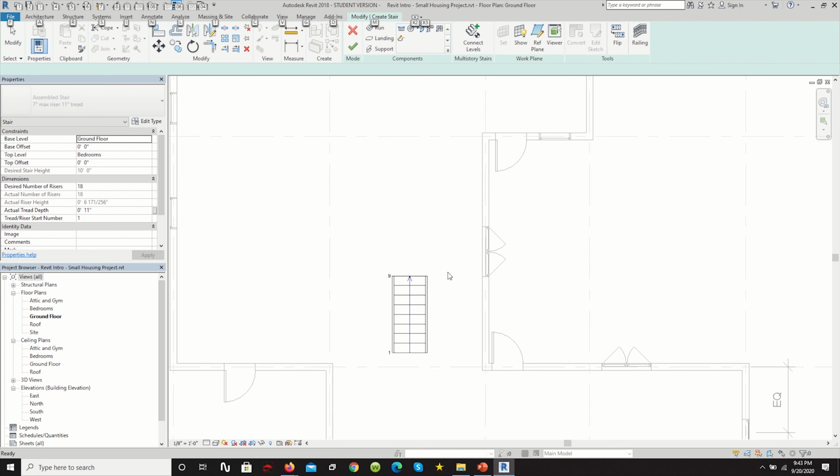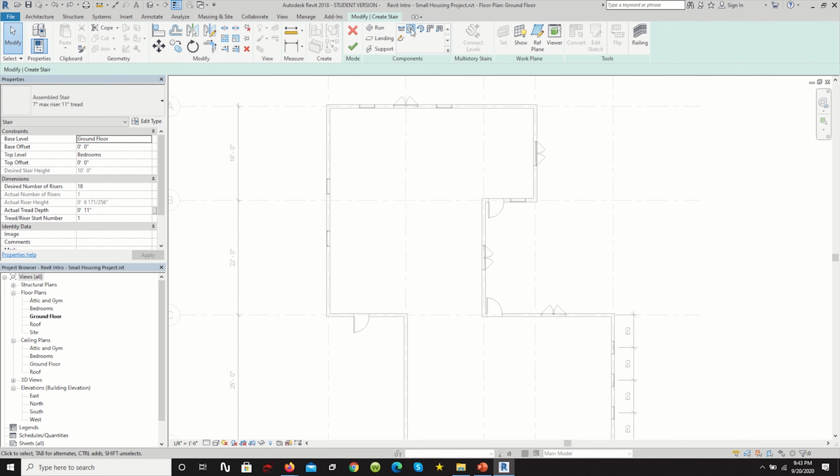And another way, Control Z, another type of stairs, you have the spiral stairs that you can work on as well. First, you pick the radius of the stairs. So do you want it to be wide, narrow? And then it just finishes it that way. And this one, what you can do is likewise, you pick the radius, and then you have control on whether or not you want to actually add a riser. You can add a riser and then finish off the stairs.